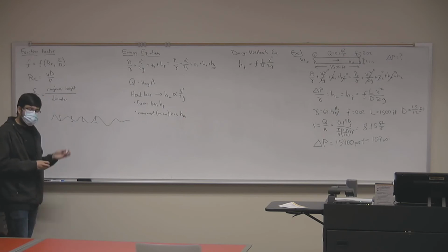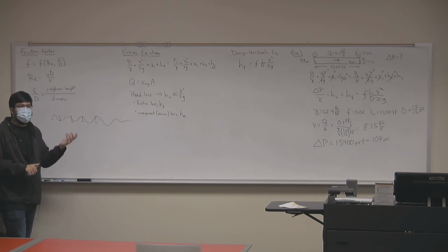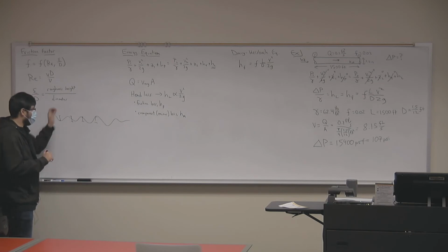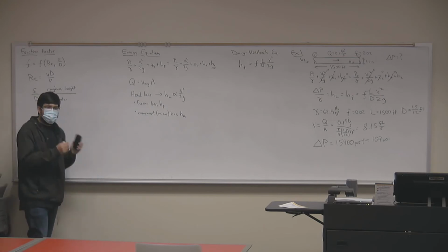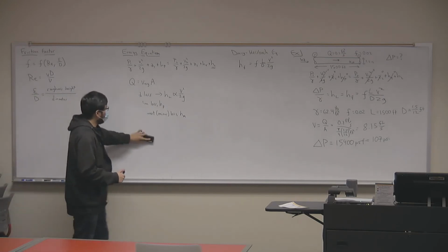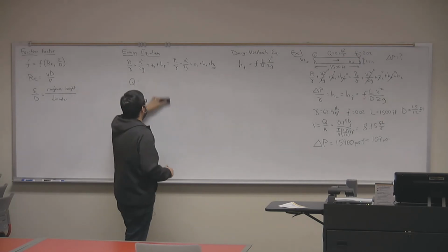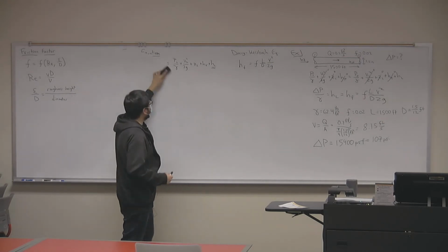Of course, given that information, how big do you think the roughness height will be for a pipe, let's say a smooth metal pipe? A really, really small number, right? Because it's so small that we cannot really see it with our eyes, okay? So don't be afraid when you see those impossibly small numbers for roughness height. We're going to be dealing in the orders of like 0.0 something millimeters, so really, really small numbers, okay?